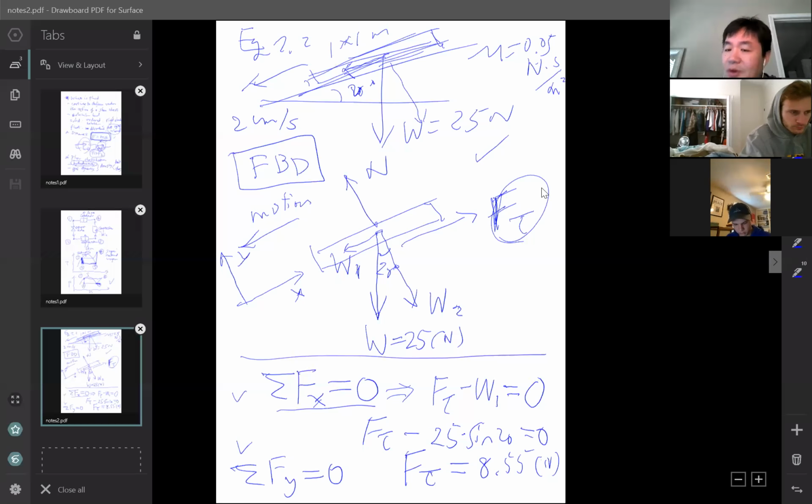Since you take the oil away from the drawing, you have to replace it by a force to represent the presence of the oil film. That's a rule of thumb, very, very important in drawing free body diagrams. You have multiple objects always, but when you draw a free body diagram, you will probably draw one object at a time. That's how to make it correct.